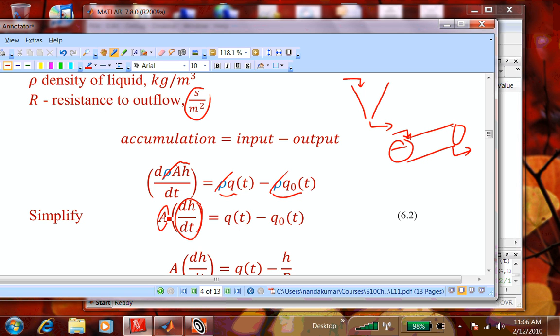When you get a second order system would be when I take this and feed it into that. So I have two tanks in series. One is a conical tank, and the height there drives the flow out, and that goes into a cylindrical tank. Now we have two first order systems that are connected. So the response of the height in the cylindrical tank is governed by what happens in the height in the conical tank. Okay? So that would be a second order system. Any other questions?